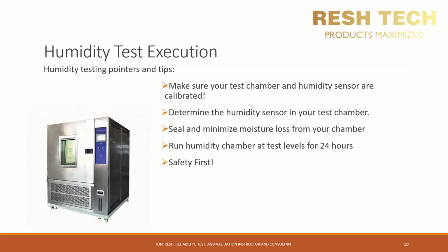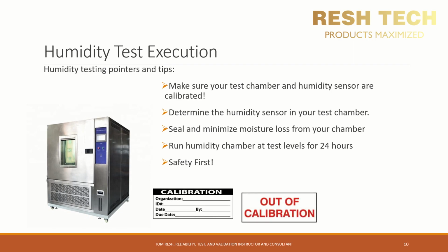Let's go ahead and discuss some pointers when performing humidity testing. The first thing you need to consider is to verify that your temperature chamber and humidity sensor are calibrated. Accuracy is important in the world of testing and measurement, so don't be like some places I've seen and have the original calibration sticker from the chamber OEM when you first purchased your equipment 5 years ago. Keep your equipment calibration up to date to ensure accuracy of your temperature and humidity measurements.